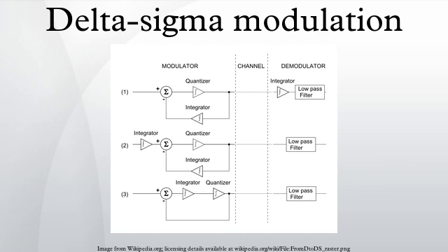Construction of the waveforms illustrated is aided by concepts associated with the Dirac delta function in that all impulses of the same strength produce the same step when integrated, by definition. Then 4 is constructed using an intermediate step in which each integrated impulse is represented by a step of the assigned strength which decays to zero at the rate determined by the input voltage. The effect of the finite duration of the impulse is constructed by drawing a line from the base of the impulse step at 0 volts to intersect the decay line from 4 at the full duration of the impulse.